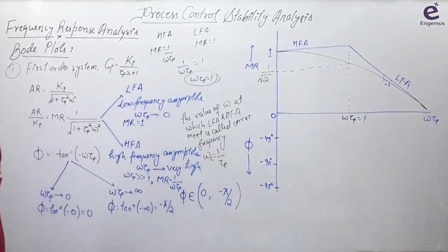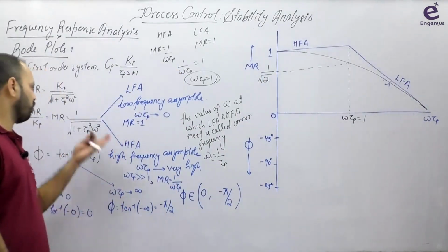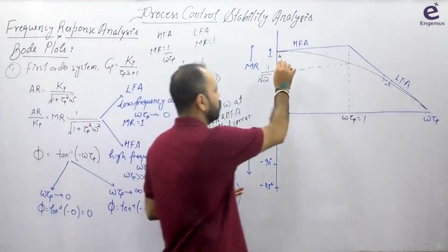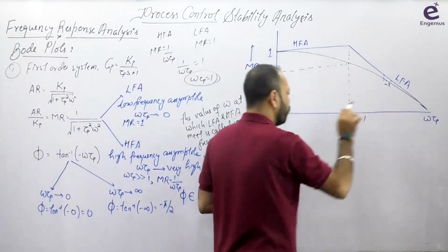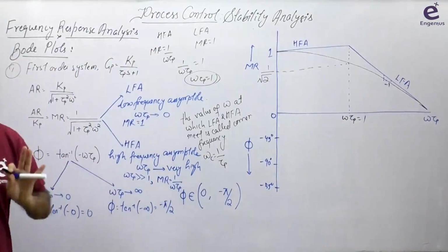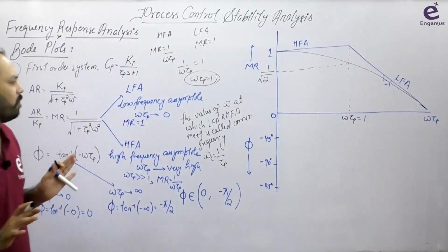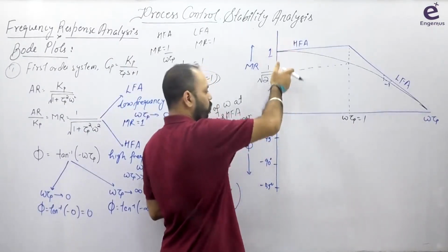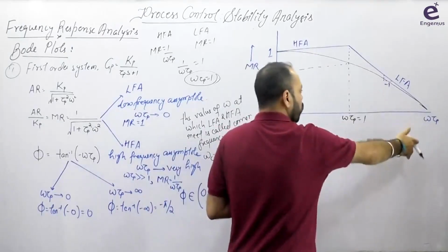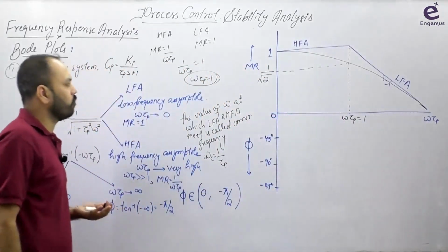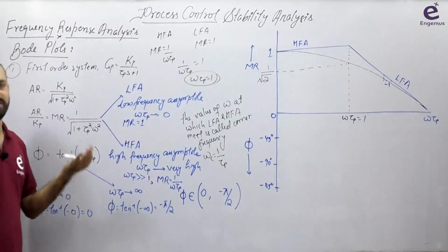This is the graph of the Bode plot. What you have to remember in the Bode plot, first of all, is how we plot it. Second thing you have to remember is the nature of the asymptote. For the GATE point of view, you can say that asymptotes are the Bode plots. Actually, it is not, but the actual graph and asymptotes are identical only for small values and very high values. In between, there is a significant gap. But still, for our calculation, we are going to say that asymptotes are the plots.